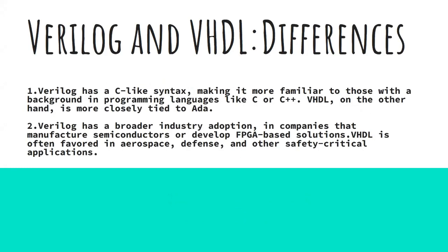The key differences between Verilog and VHDL are that Verilog is based on the C language and VHDL is based on Ada and Pascal languages. Just like VHDL, Verilog is used to design electronic systems. Verilog is not very case sensitive, and VHDL is not case sensitive. Verilog is less complex compared to VHDL. Verilog is a newer language, and VHDL is older than Verilog.